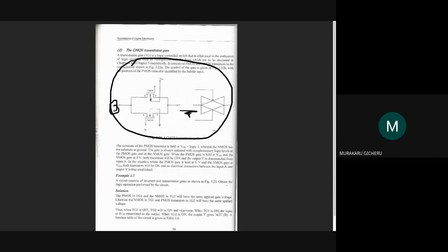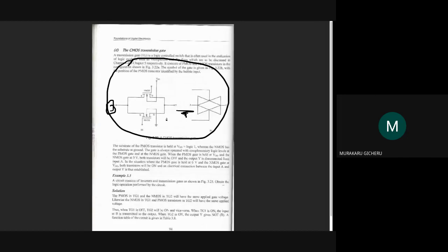And whenever there's a 0 here at NMOS, it's going to be a 5 here at PMOS. And if there's a 5 at PMOS, you won't be able to form the channel and conduct. And if there's a 0 here at NMOS, you will not be able to form the N-type channel and won't be able to conduct. Is that good enough, Situne?